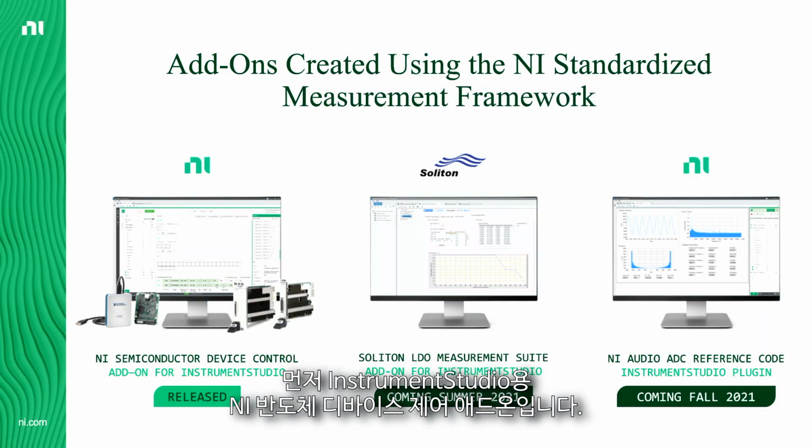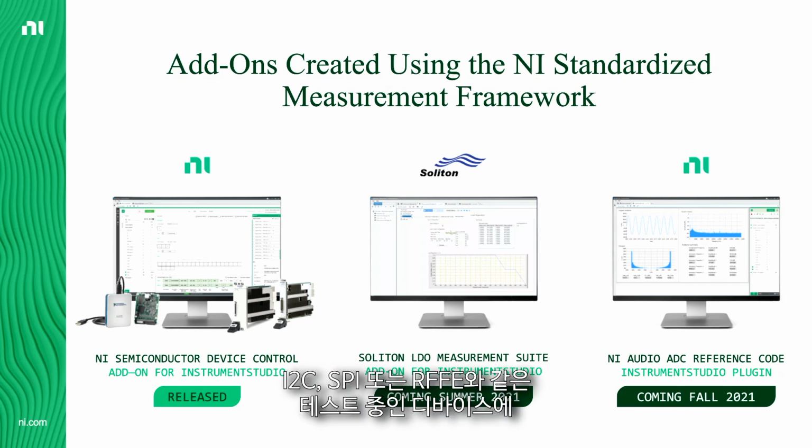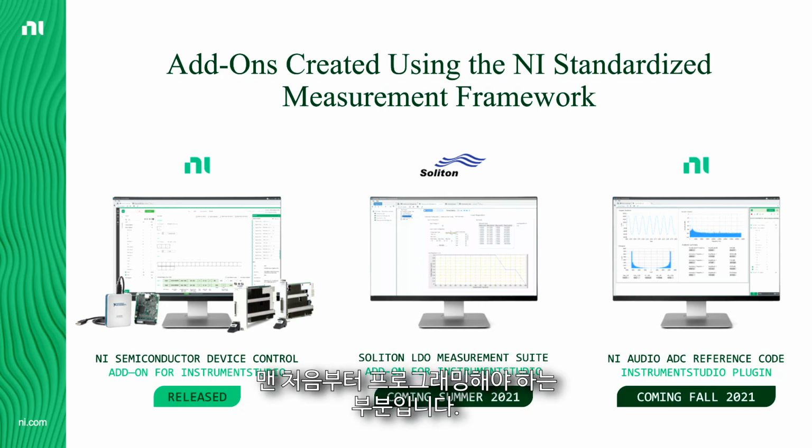The first is the NI Semiconductor Device Control add-on for Instrument Studio, and this is actually released now. If you think about most mixed signal ICs, one of the most common things you have to do is interface with that device and speak to it. That includes things like powering on the part, perhaps closing relays or toggling elements of your load board or your eval board, and then ultimately speaking some digital protocol to the device under test, like I2C, SPI, or RFFE. And that's something that almost every mixed signal validation engineer typically has to program from scratch.